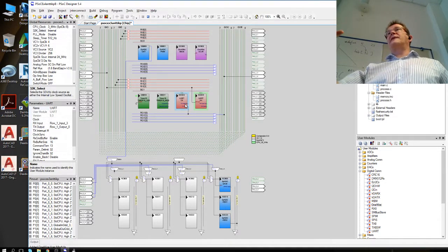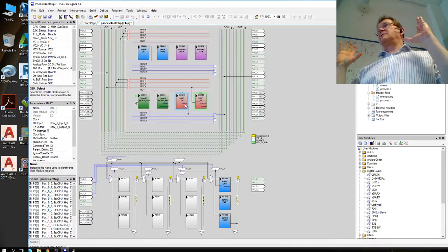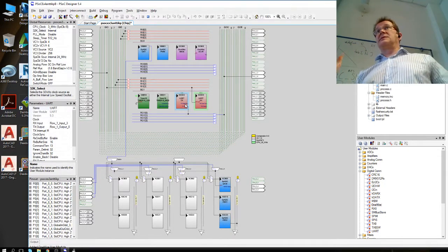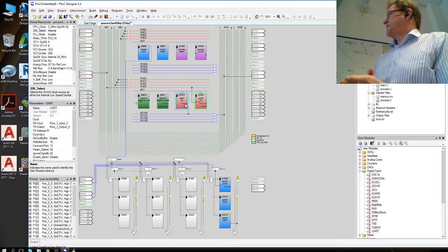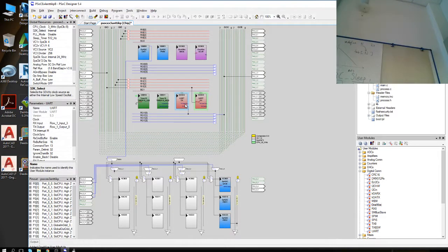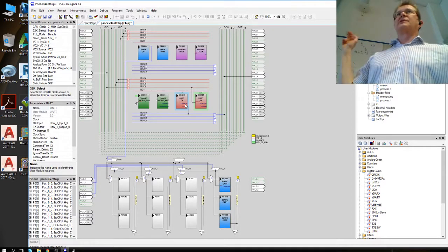There's also a software buffer that you can use to send strings using this UART. That helps a lot with the protocol. Otherwise, if we had just the UART circuit and code, the UART works such that you send one character by character, and you have to wait until the previous is gone before you can write your new one, unless there is a first in first out buffer. But this has the first in first out as a software buffer.